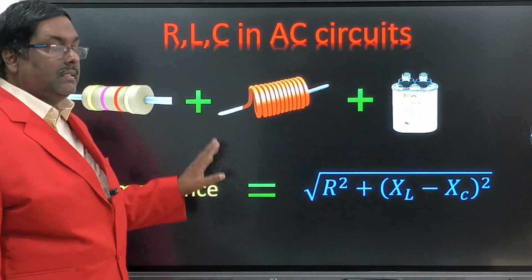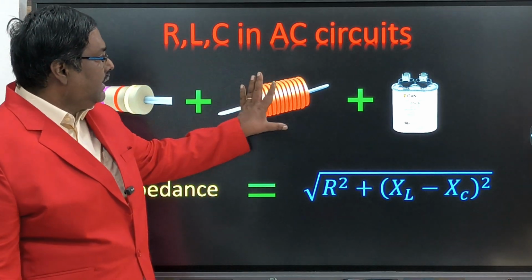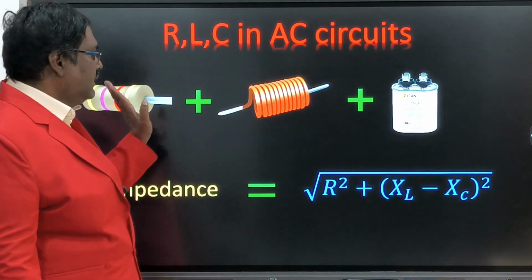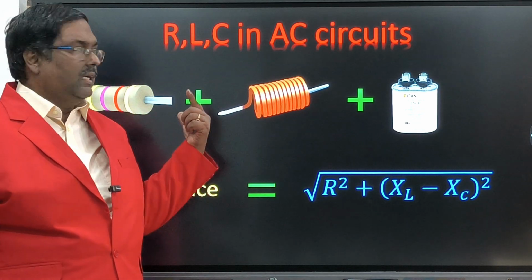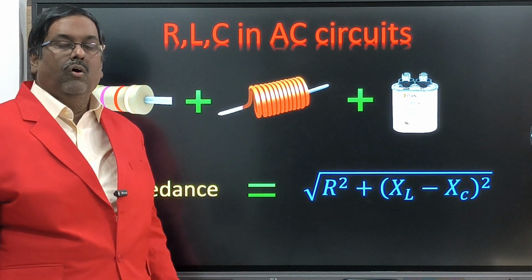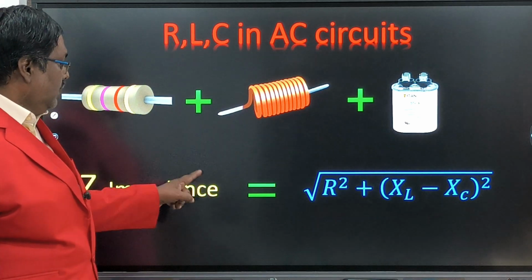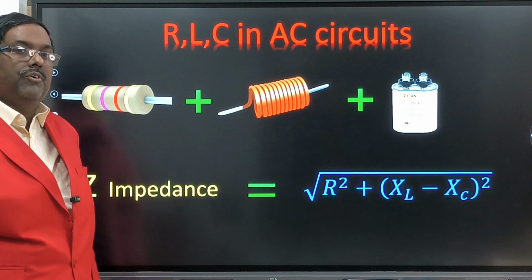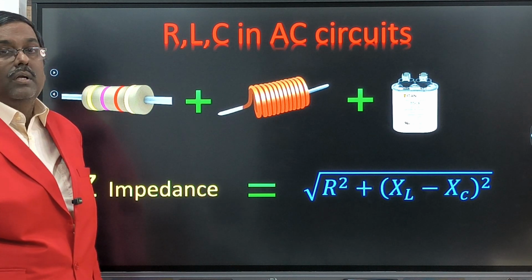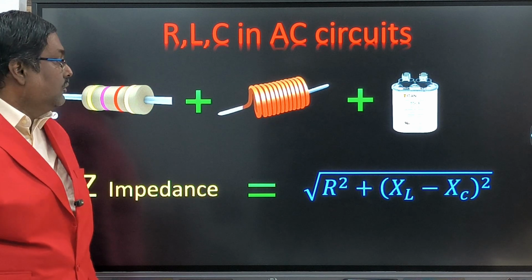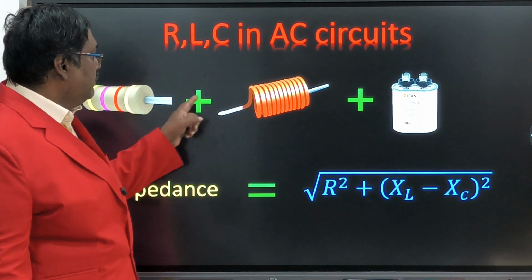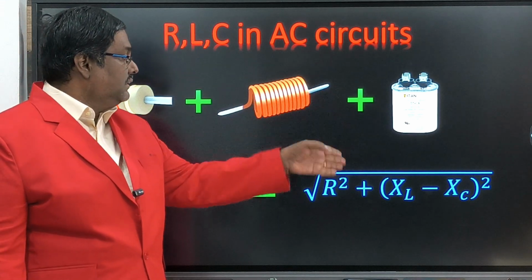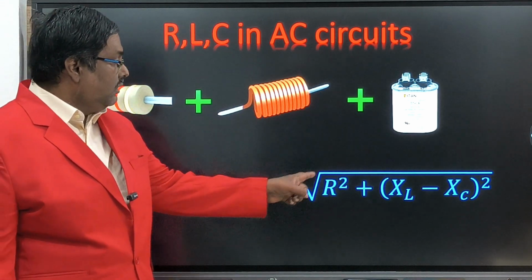So impedance is a combination of resistance, inductive reactance and capacitive reactance. Okay, here capacitive is not there, only inductive reactance and resistance. Whichever resistance is in the line, if you add it all together, the total will be the impedance. So you have to use impedance for the calculation, not only resistance or only reactance. So how to add it? Because the resistance is linear, the inductive has a 90-degree direction difference, and the capacitive has a 180-degree difference from it. So this is the method of adding.